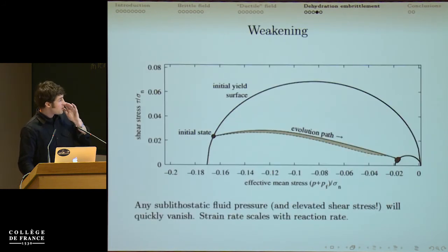So now I'm going to plot a failure envelope. Again, it's going to be a shear stress versus effective mean stress plot. I was working with civil engineers, so they like to plot positive stresses in tension.